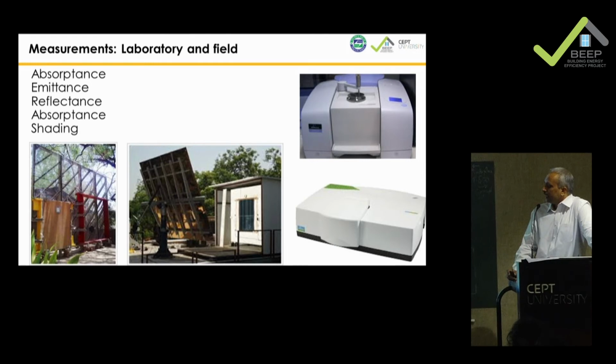What we do is, and again you will see these, this is a spectrophotometer and FTIR. This is where I did show you that the roof coating we measure. Same machines we use to understand how much light and heat gets transmitted through glass, gets absorbed by glass, and gets rejected by glass at each nanometer. Right? So these two help us to do that.